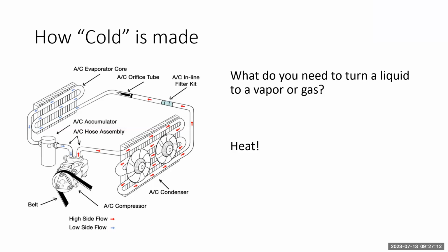Right. Because from time to time in the past, like last year, I did 4 or 5 compressor jobs where the customer was infuriated with another shop, and sure enough, as soon as I took the manifold line or the combination line off the compressor, it was just saturated with metal. So there are other kits too, since you're talking about screens, that you can install, because the aftermarket has a lot. There are many different companies, like Murray and so on, where you can actually put a screen on the inlets of the compressor as well to protect the compressor.